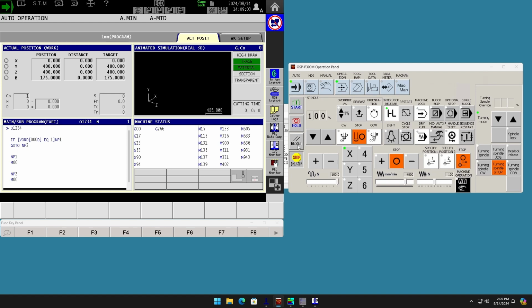All that this guy had to do was put the tool in. It was just a new drill. And the other step of that was to also touch off the tool. So I added this in here so that when the operator held down the interlock release button and pressed cycle start, what would happen is it would look at the current tool in the spindle and clear the not good tool state for tool life management.